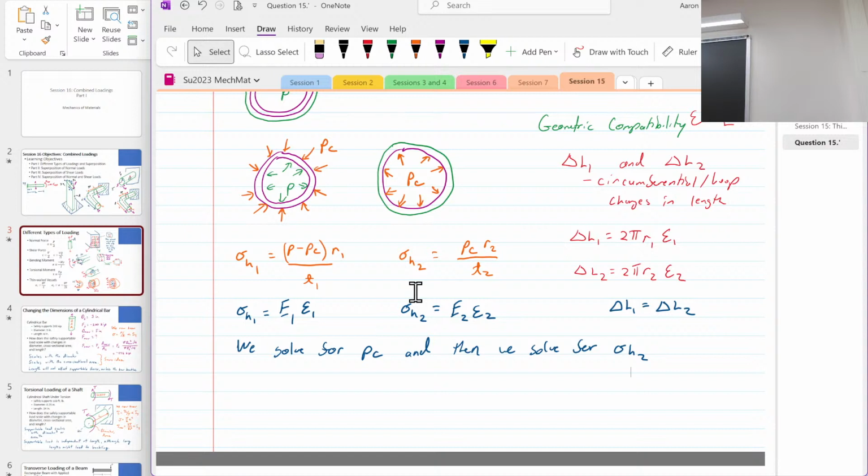What's L? Why is it just one? The general rule: always work in meters. So for everything, meters, Pascals, meters. So, simple. What's S? And you're using J of pi over 2. It's just pi over 2 c to the 4, right? And then for the area, pi c squared.